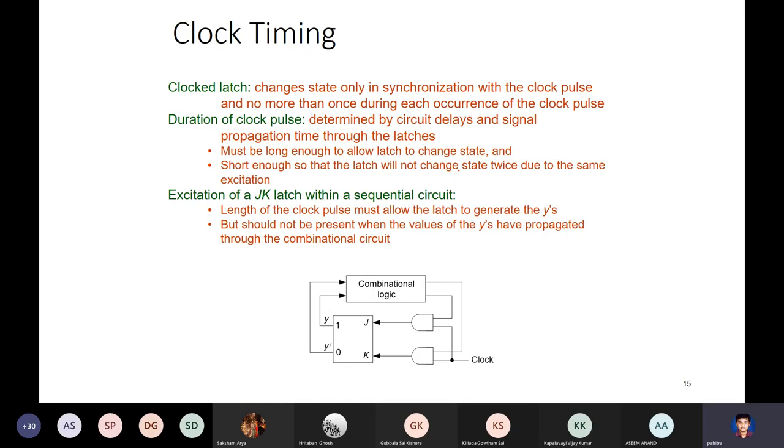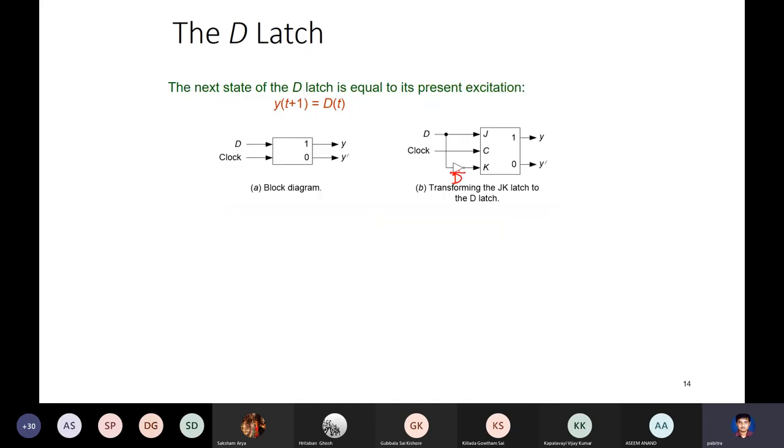Now, 4 types of latches we have studied: the SR, the T, the D, and the JK. And we have also studied a clock enabled latch, which means the timing diagram will change only at the clocks, only when the clock is on. Just think about this carefully. And each of these 4 types, the D, T, SR, and JK, I think you have fairly understood. Let me summarize it quickly.